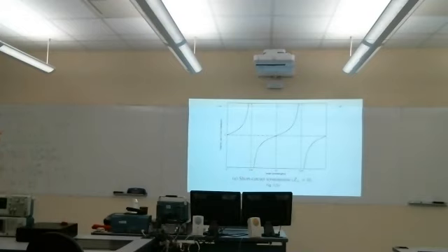And again, although our characteristic impedance Z0 is real, ZL can be anything. It could be an inductance or a capacitance, a pure reactance. It could be a resistive load. Remember, we looked at the special case where if ZL is equal to Z0, that's the matched case. There is no reflection. Gamma is 0. There is no reflection in that case.